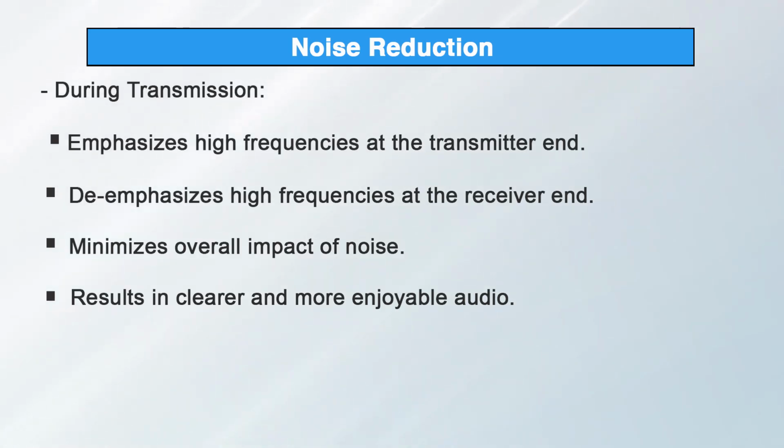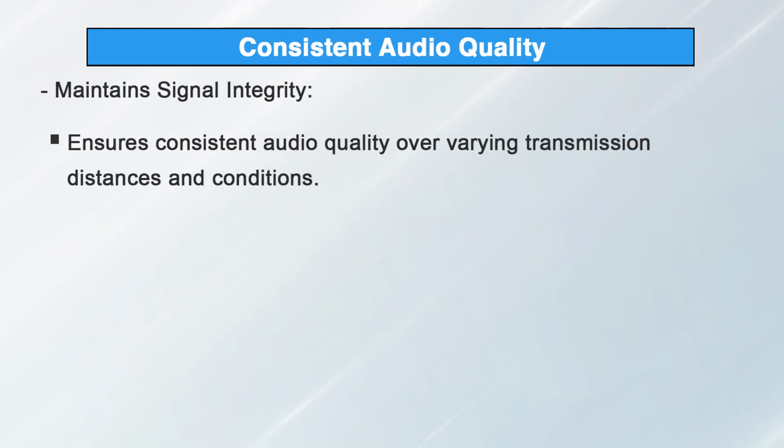This process effectively reduces the noise in the received signal, resulting in a clearer and more enjoyable audio for the listeners. Additionally, the use of pre-emphasis and de-emphasis helps in maintaining the integrity of the transmitted signal, ensuring that the audio quality remains consistent over varying transmission distances and conditions.